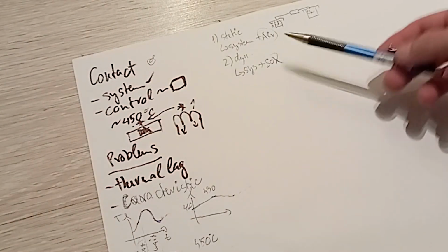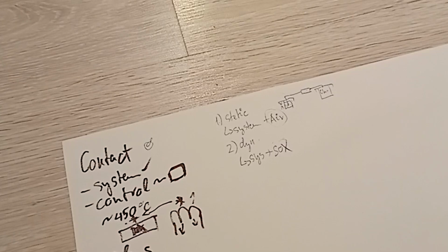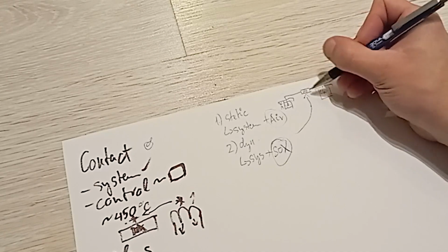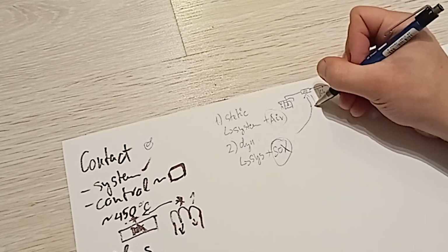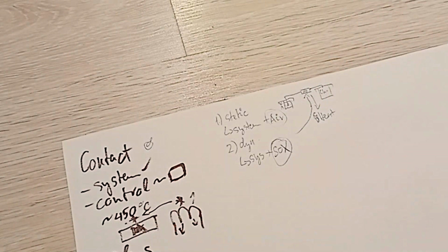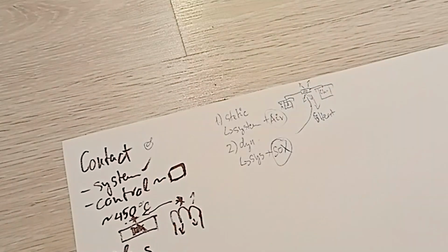So the sulfur oxides are a bit tricky in that as they travel through the system that I have drawn previously, the problem is that the SOx reacts here at the catalyst bed, and it generates heat through the chemical reaction.